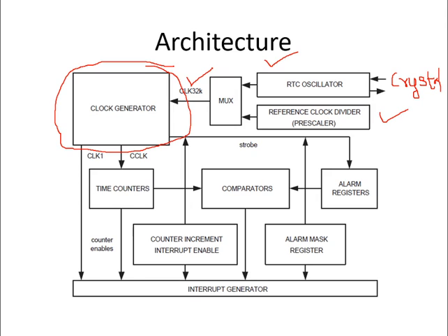The second explanation is that it's commonly used. Naturally you have a standard crystal which is used in all clocks to generate a 1 second time pulse. When you give a 32.768 kilohertz clock signal to any circuit using that crystal, you can generate exactly a 1 second period. That is the reason this is used and that it is commonly available in the market. That may be the reason this particular frequency is used.